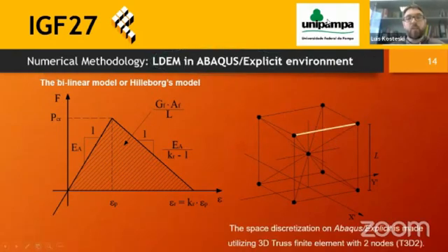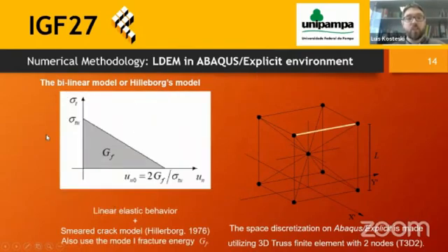We use this method in Abaqus Explicit. We put this using a law that is available in Abaqus. All the lattice is modeled by 3D truss finite elements, T3D2 elements.